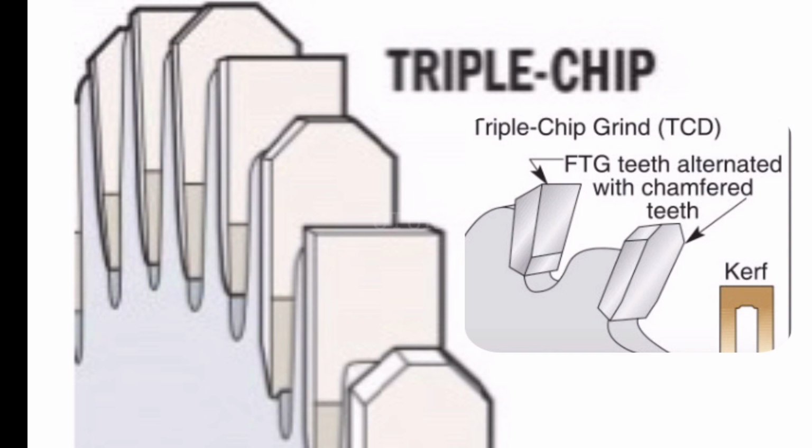Good quality cuts from the TCG on the melamine will often result in a fine smooth cut quality along the top edge of the melamine, which will have pristine sharp corners, which is the pro. The con is, as the blade exits the bottom side of the melamine, it may chip off a little bit as it exits the plasticized bottom.